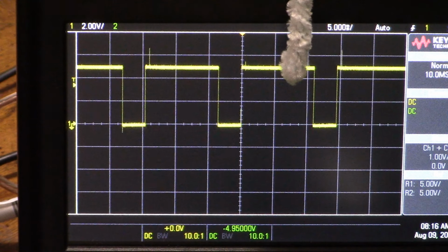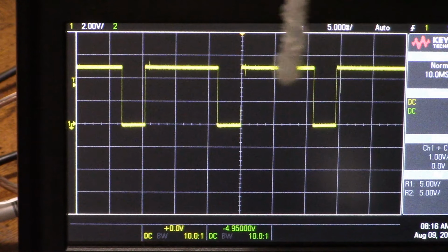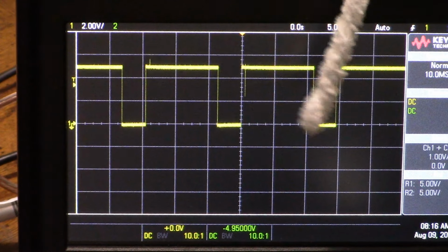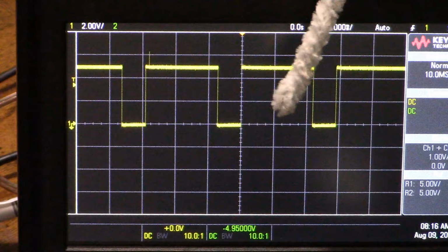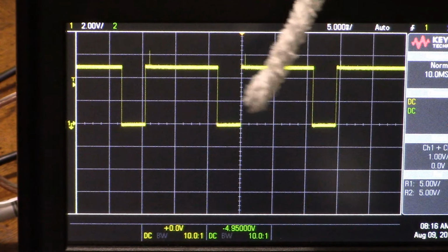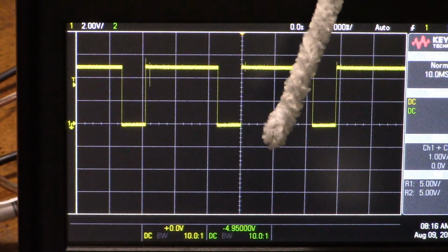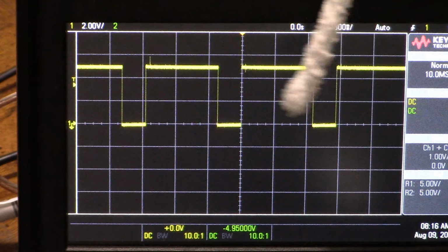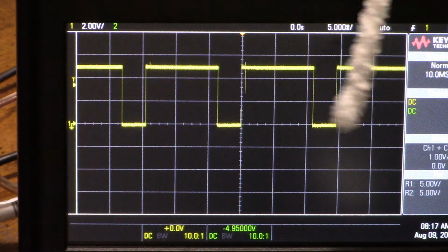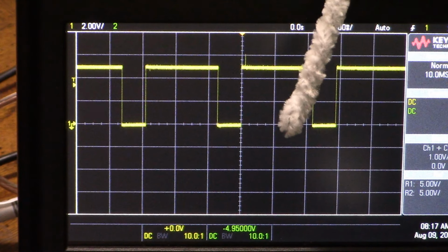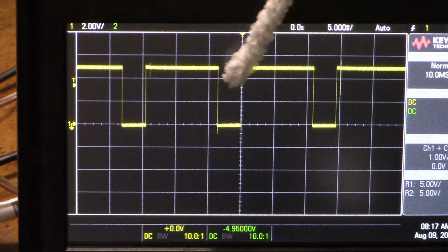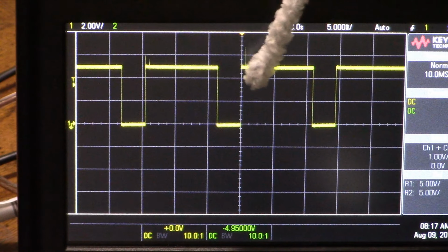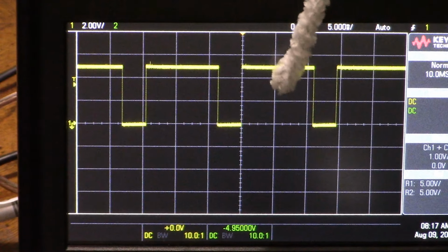So that's just something to keep in mind, is you're going to want to adjust for the fact that it's logarithmic in your software. If you have software control for the percentage here, and volumes are like this too. If you've ever noticed when you're on your computer, if you have the volume down towards like 15% and you turn it down to 13%, then it's a big change. But if you're up at 85% and you put it at 87%, it's a much smaller change because they're just using a straight percentage factor on something that's logarithmic, and that's dumb. So it's the same thing here. If you want percentage duty cycle on a linear scale, you have to use an exponential function to counter the logarithmic voltage-time relation.